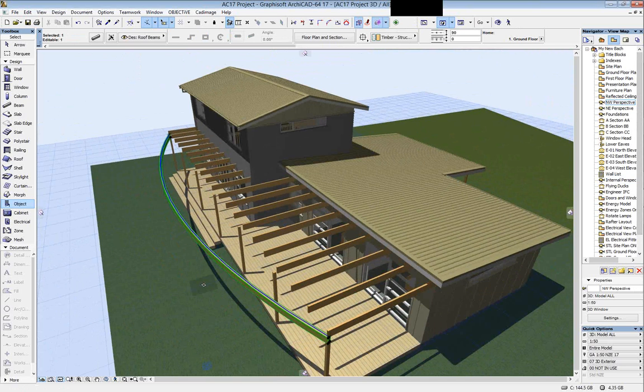So anywhere where you want to extrude something along a horizontal surface, could be a gutter around a curved portion of your project, could be a driveway or a footpath on a flat surface. Remember, it has to be flat. Just set up the profile, do your wiggly spline shape on your plan, and the driveway will follow that. If you do want to do it on an inclined surface, you can stamp the mesh, you can use the CADimage extrusion tool. There's still a lot of other options. But I think curving a beam is well and good, but using the curved technology in the beam tool and applying it to a complex profile is very powerful.